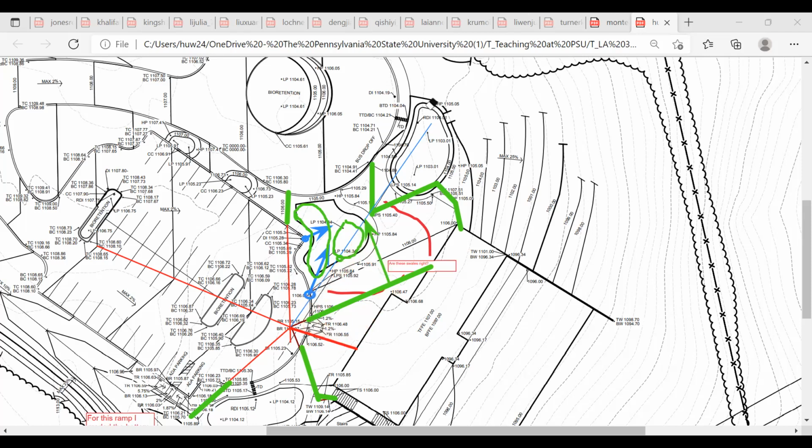So this portion, that little portion will drain down to the curb, and the other will drain down to the relatively clean cell. So that's the best solution if you can separate them. And the water level here would be lower because your entrance is lower, right? The water level here in this cell, it's higher, which is good actually. This dirty water would not flow into there. Of course, you would have some berms in between, so there would not be kind of interaction of these water.